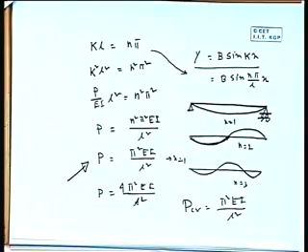So for the fundamental mode, that is the value, and these are the shapes of your buckling modes, fine. Now this case we consider as one of the basic cases or fundamental cases, because it is a symmetrical case, both the ends are hinged, and we are getting a nice expression pi square EI by L square, that is the critical load.